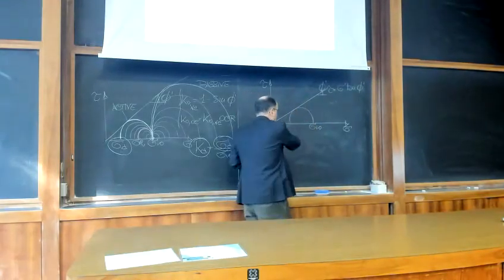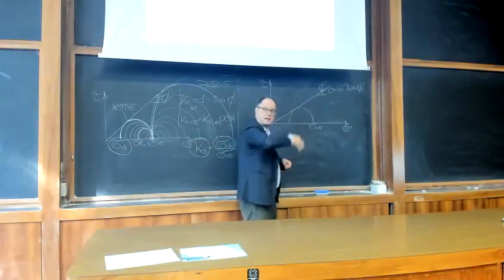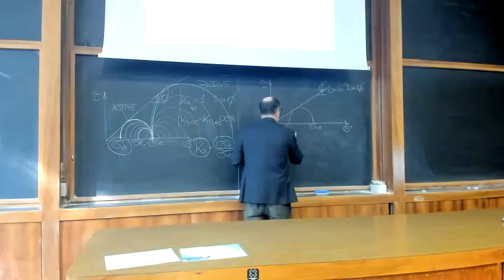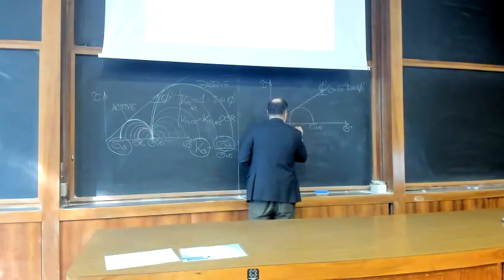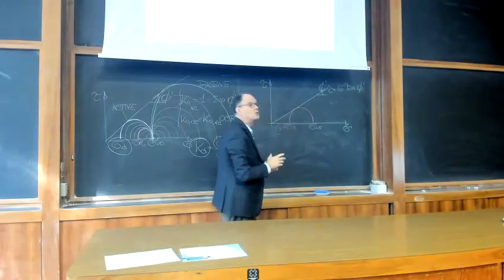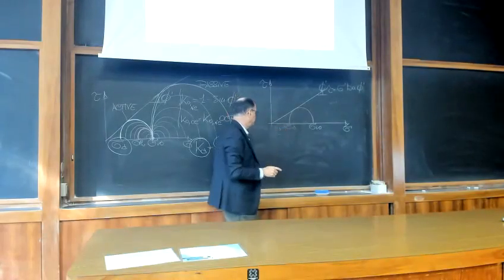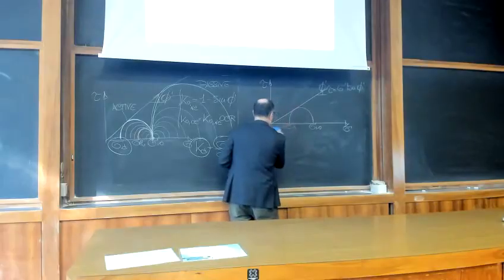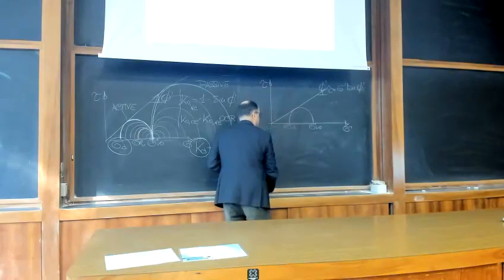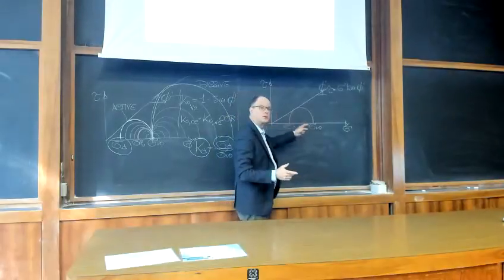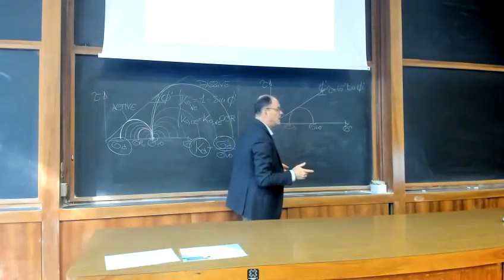So you can have any circle like that, changing your depth z, and then you have your horizontal sigma a. And you want to know the amount of sigma horizontal in this condition, that, as I have just said, is statically determined by this tangential condition. Okay?